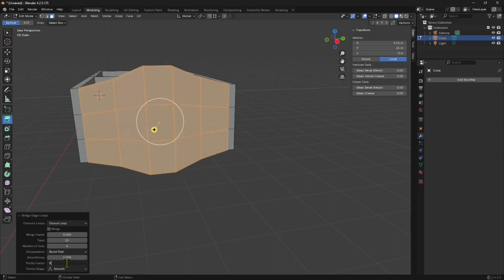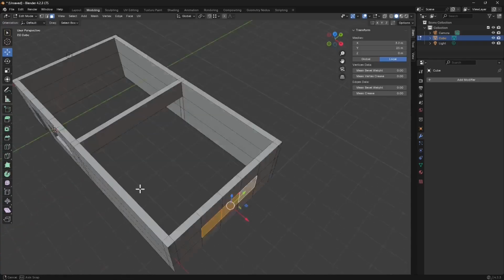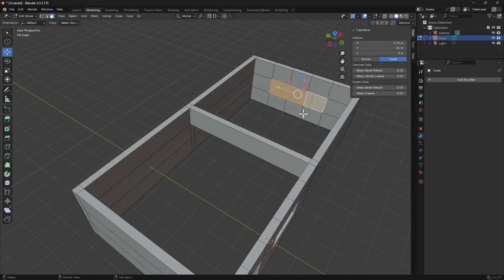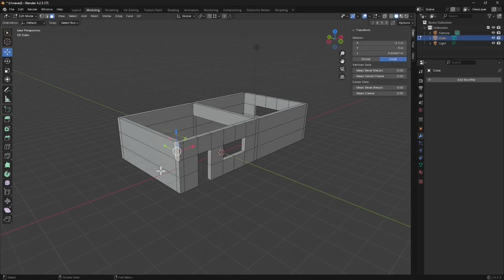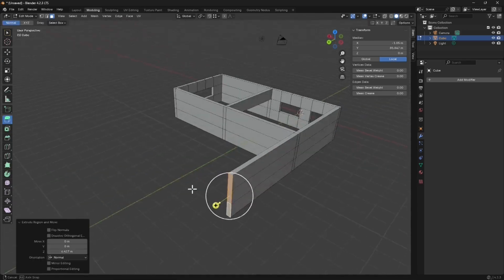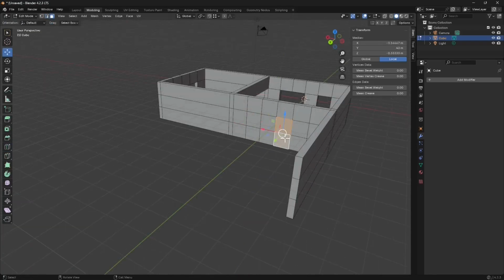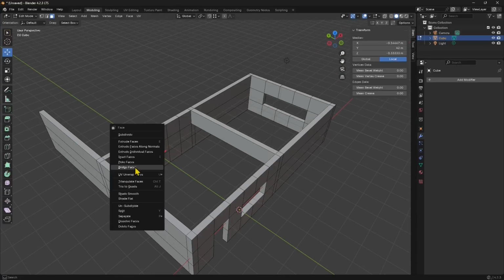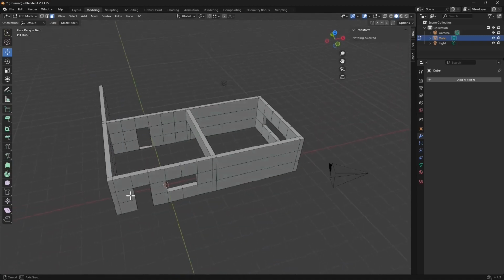I'm going to keep it simple because I want to close this architecture. So what I'm going to do is, again, select now the faces I want to remove. So let's say I want to create a big window here, and then select the three, right click and bridge. And I can continue like this forever. I can create again an entire building. I can go up and create more floors, or I can extend this horizontally, creating other rooms. And then I loop cut to create cuts, and then I use the face selection and bridge to create openings between rooms, etc., etc. It goes forever. Be careful there not to mess up the parameters so it doesn't create strange stuff.